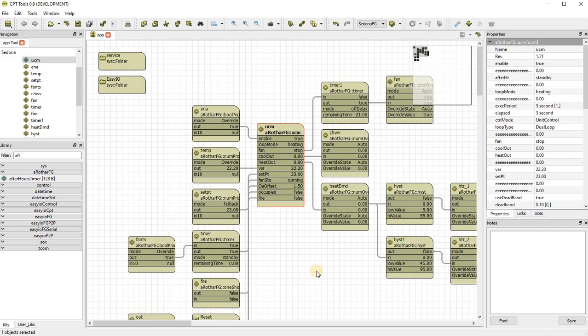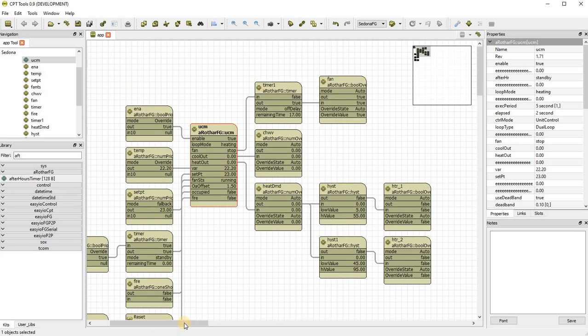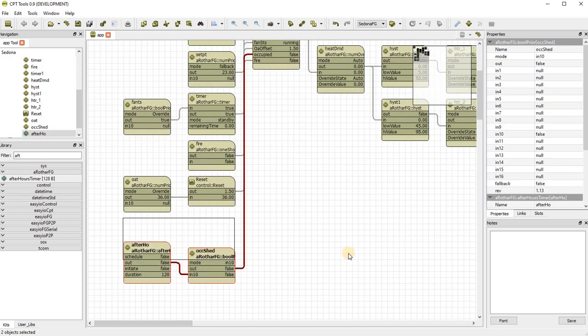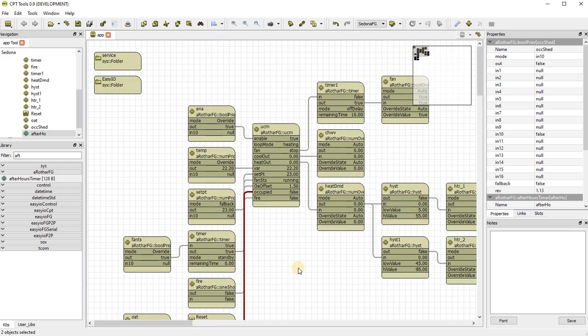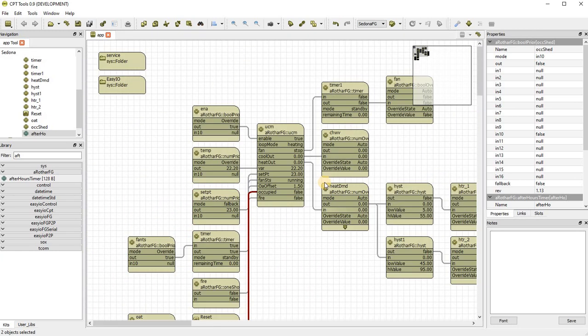So in the last half hour or thereabouts, we've got an AHU program here that runs a setback strategy, outside air offset, fire control, heating and cooling control with split loop modes, one in proportional only and one as a PI control. Didn't really take that long, did it? It looks pretty neat, and that's pretty not really neat. I'd like to spend more time on that, but OCD gets in the way.